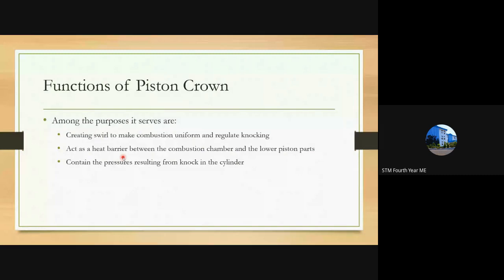In some pistons, you can see the piston is made of two materials. The piston crown will be made of one heavy material that will be able to withstand heavy temperatures, such as stainless steel or alloy steel. But on the piston skirt and other parts, different materials such as an alloy of cast iron or an alloy of aluminum are provided. The basic contact of high temperatures will be with the piston crown, so the piston crown is the only part that will be given